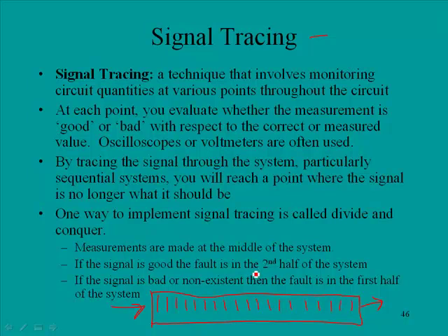Or we could just go in and say, let's measure right here, and make a determination: is that a good signal or a bad signal? Again, you have to be familiar enough with the system to determine that. If it's a good signal, then you know the problem is over here, so you'd divide and conquer again and determine whether it is here or here. That's the concept of divide and conquer utilizing signal tracing.